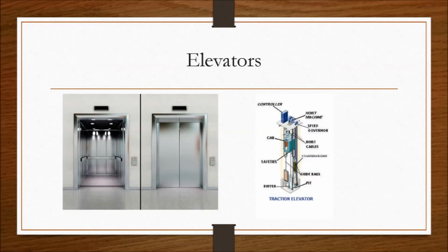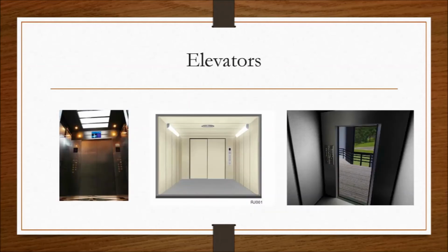Elevators. Parts of elevators include cab, shaft, counterweight, elevator machinery, control panel, speed governor, limit switch, buffer, hoistway door, operating controls, car signals, and supervisory controls. The goal in lighting a cab should be to provide pleasant, even illumination from sources that are resistant to vandalism and abuse. Elevator controls and mechanisms are complex, diverse, and subject to heavy wear. They are designed with large safety factors and require thorough and frequent maintenance.